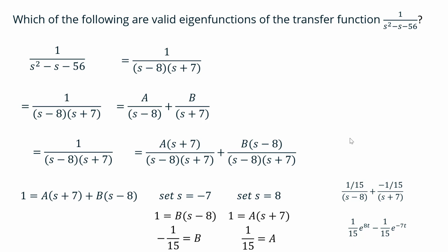You might say, why is that? The reason for that is because this actually ends up being a transfer function. The impulse is 1 in the S domain. So you're basically taking 1 times that to chain together the impulse as the input and then the transfer function here. If you want to do a step response, then it's a little bit more complicated. Usually, the impulse is easy enough to do by hand. If you want to do a step response or a sinusoidal response, then you might as well simulate it. It's harder to work out by hand.